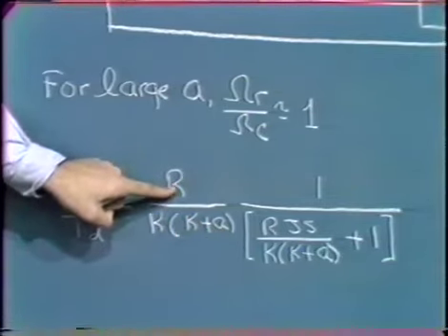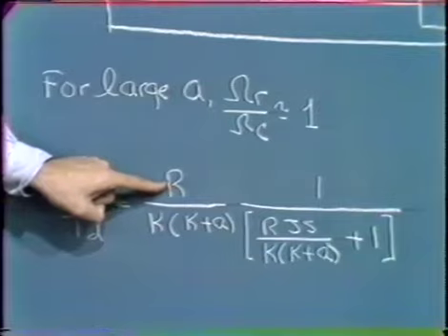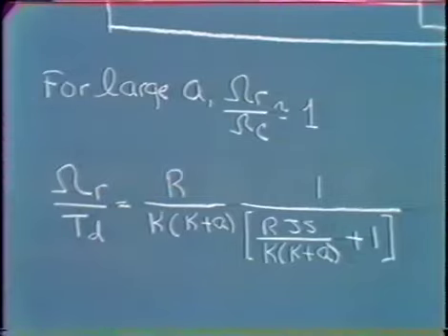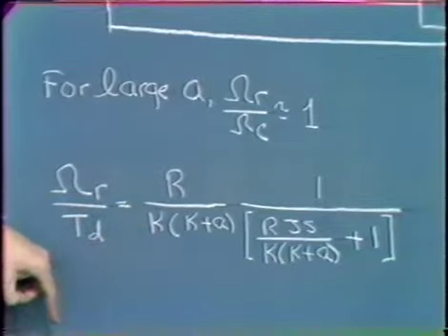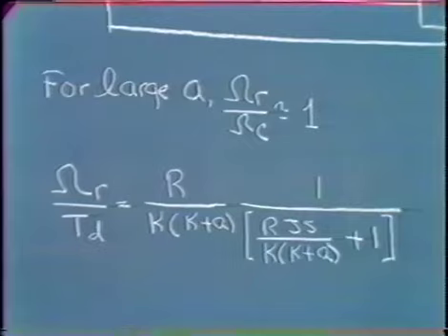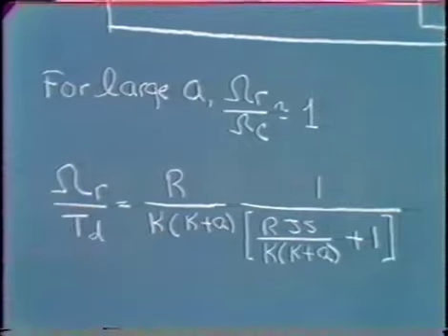Similarly, if R is smaller, the motor itself experiences greater armature current and hence provides greater torque for a given voltage applied to the motor. And so that's the reason that R appears as it does, a smaller R leading to smaller disturbances. Similarly, if the back voltage coefficient is larger, the motor sort of intrinsically tends to minimize disturbances applied to it, velocity disturbances.